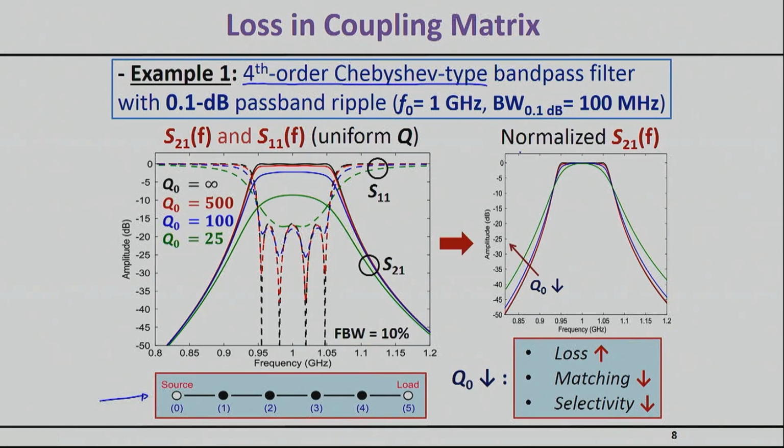It's a filter that basically has a relatively wide fractional bandwidth. If you see, its center frequency is actually 1 gigahertz, and the fractional bandwidth is 0.1 gigahertz. So it basically has a substantial fractional bandwidth. So it's a relatively wideband filter, in other words. And here you can actually see its insertion loss, or the filter response to be more precise, for building this